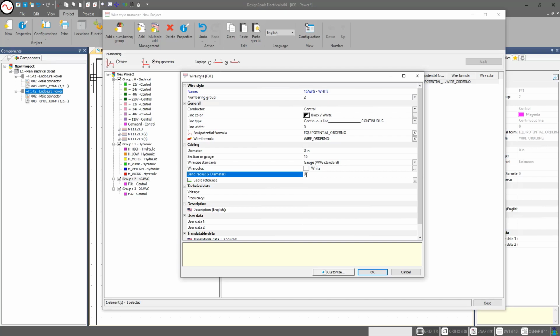Things that we would most likely want to put in a bend radius for is obviously larger diameter cables, wires such as maybe 12 gauge, 10 gauge, 00, those larger sizes that we work with. Fiber optics or RF lines are important too, to make sure we don't snap those lines. So the more information you put into these, and this goes for manufacturer parts as well, the better results you're going to get inside of your bill of materials and your to from wireless going forward.